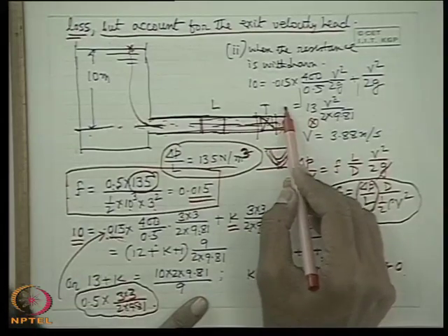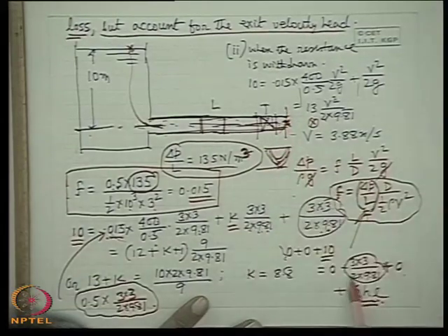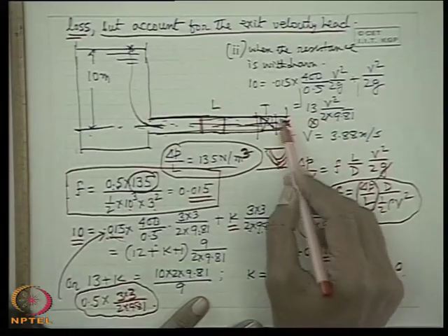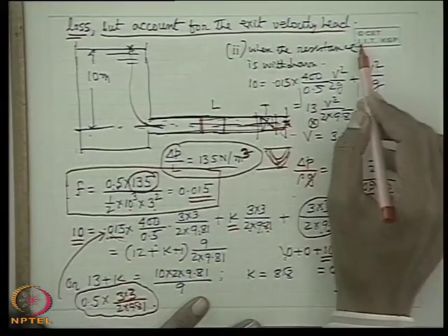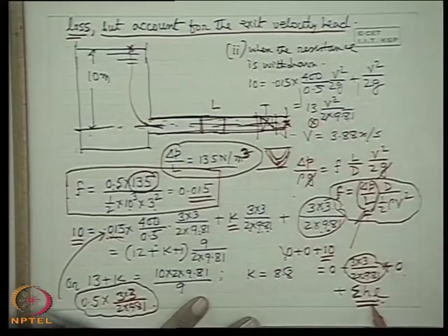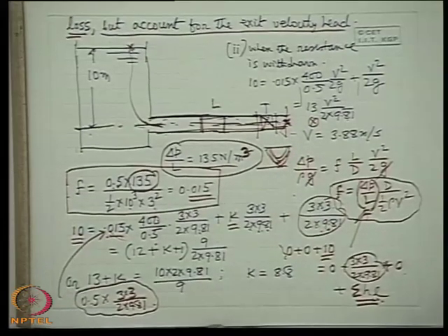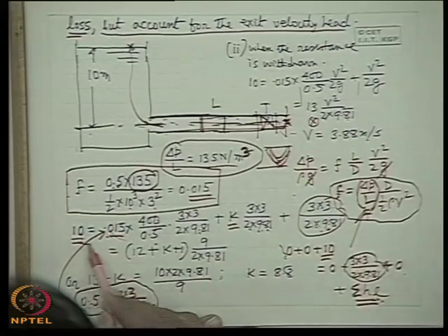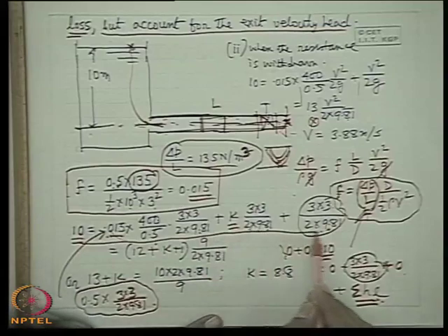So if you write the Bernoulli's equation here, then it appears as the velocity head. For example, if it is connected with another reservoir, and if you write the velocity head at the far end where the velocity is arrested, then it will be the exit loss there. So this will be the same equation we get whichever way we put it.